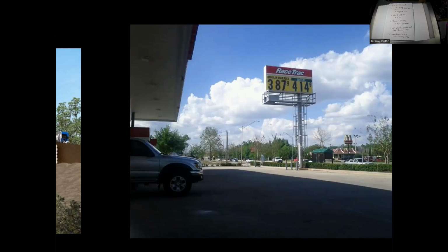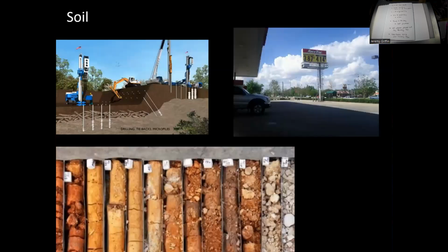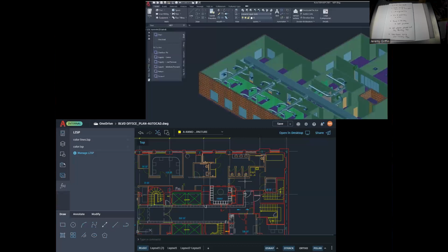Now, there's actually an equation that goes along with this. It depends on what size of hole we're using and what kind of soil you have underneath. There's a lot of other factors too. What's the weight of the sign on top? But yeah, a good rule of thumb is about a third of the height of the pole above ground. That's what you want to go underneath.